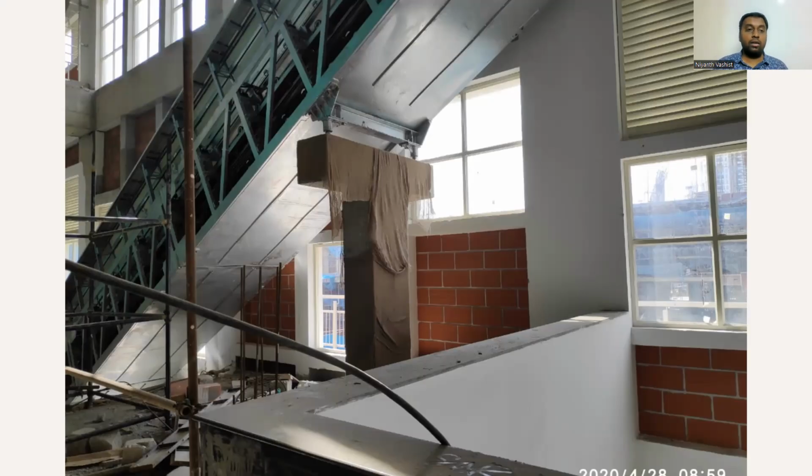Right here, if you look at it, this was one of the first stations where we had clay bricks instead of blockwork, either concrete block or lightweight or AAC blocks. So we had porotherm clay bricks here just to increase the aesthetics of the metro station. Sometimes you can have a total steel structure also. The metro stations in Riyadh or in Dubai are majorly steel structure, and even that works out as well. Now, this is the simple understanding of components available in a metro station.